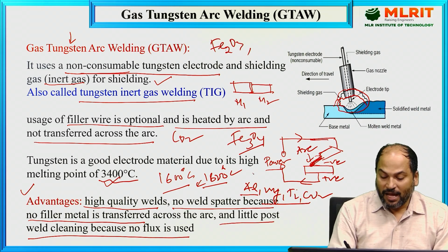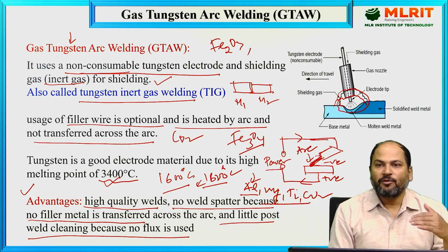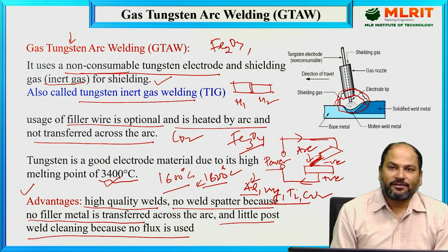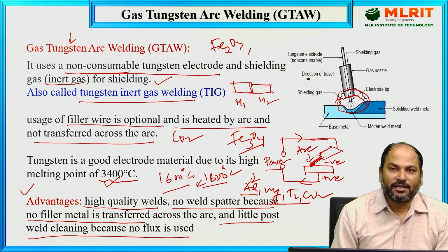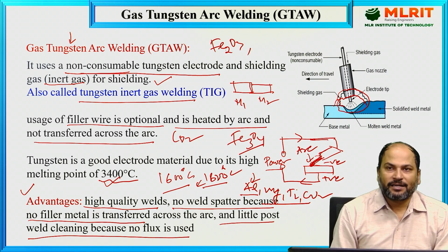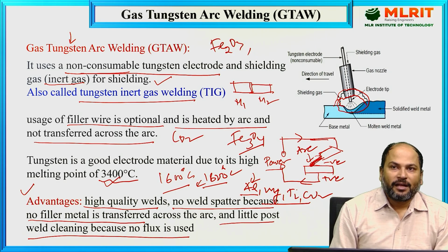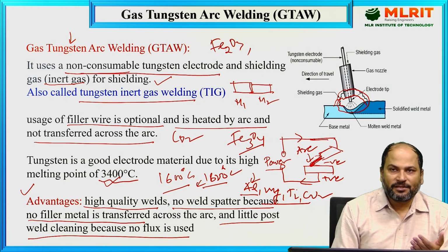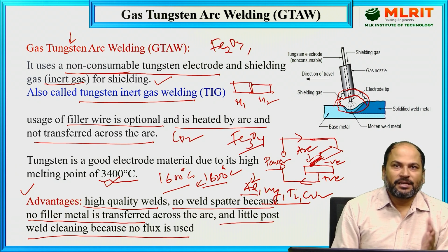For example, aluminum: if the temperature is more than 400 degrees centigrade, then what will happen? It will start to oxidize. If oxidation starts, again brittle oxide will form over there, which will further reduce the strength of the material, or maybe it will create brittleness in the structure wherever we are doing the welding. So whenever it is used in a particular application, it will create problems.